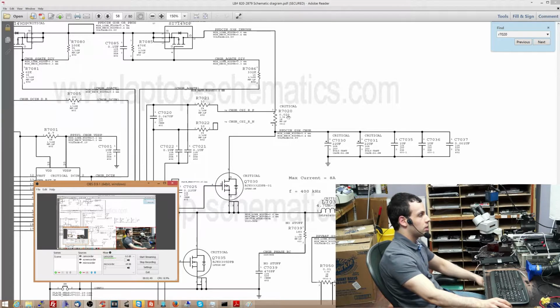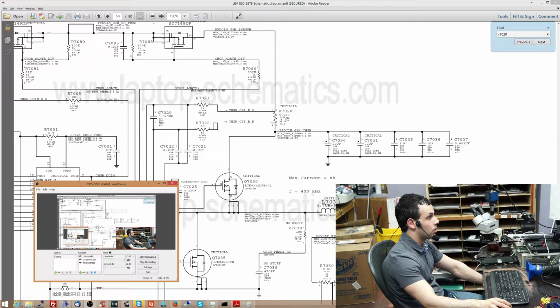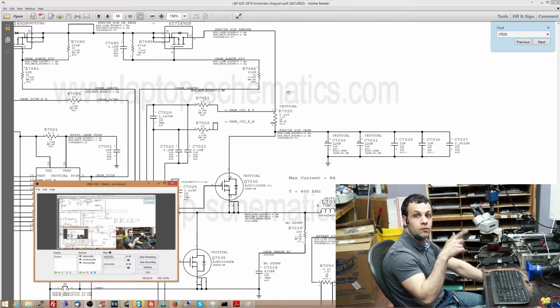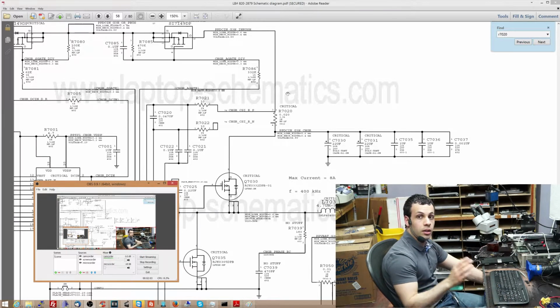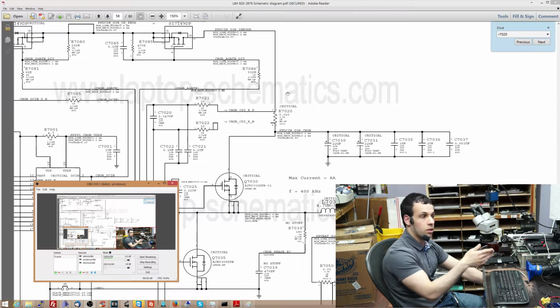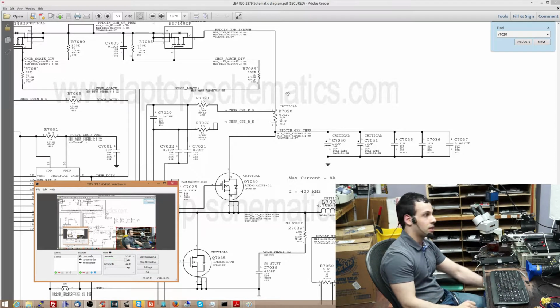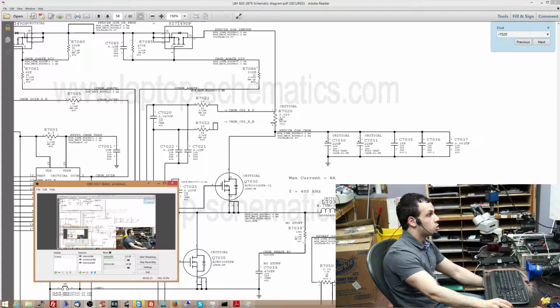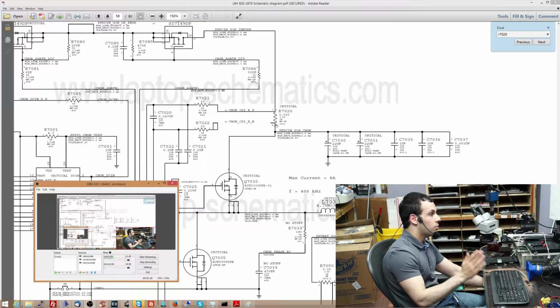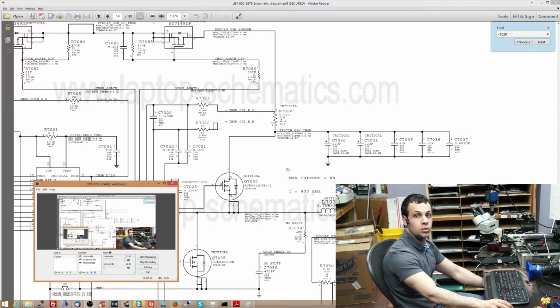This is a really, really low impedance resistor, 0.02 ohms. That is a very, very low resistance resistor. It's not going to have a lot of effect on the machine, but what it will have is a voltage drop across it. Now, the thing with the proper current sensing shunt resistor is that it is going to have a voltage drop across it that is directly proportional to the amperage being used by the computer. Let me repeat that. The voltage drop from this end of the resistor to this end of the resistor is going to be directly proportional to the amount of amperage going through the resistor.